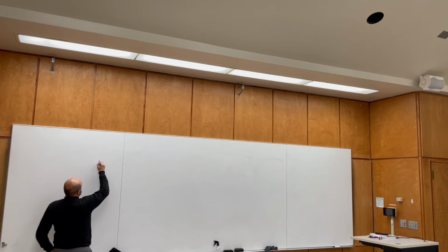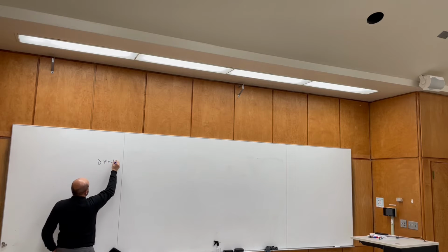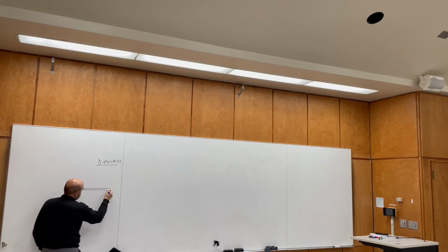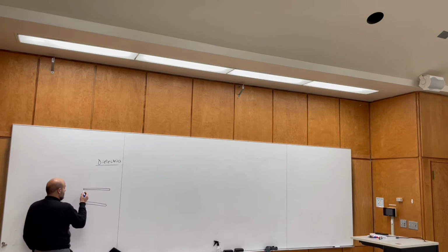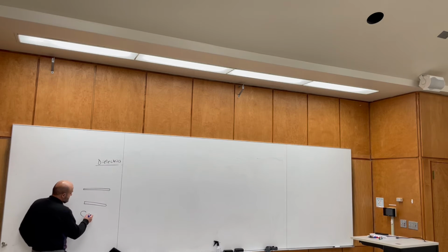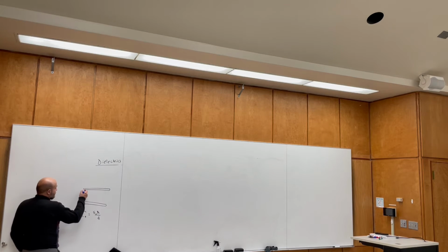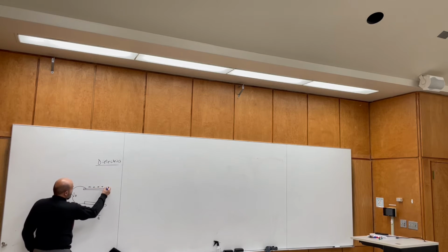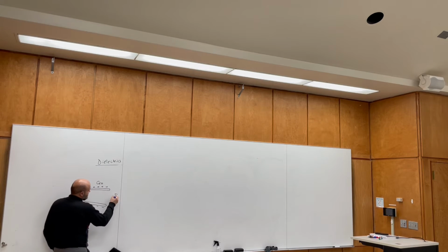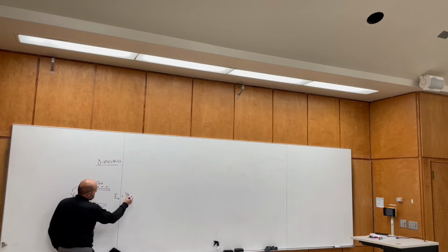So this is under dielectrics. So we have the plate, or the two plates. Now we have C0, and here I'm going to use 0 to indicate that we have air between the two plates. And this is epsilon 0 A over D. And now if you connect this to a voltage, I'm going to call it V0 because we have air. This is going to create Q0 on each plate.